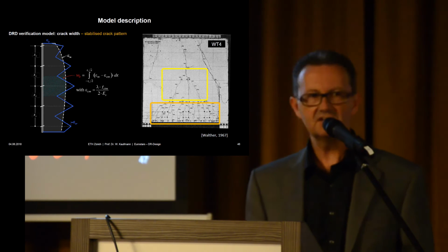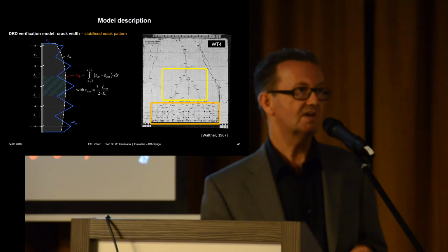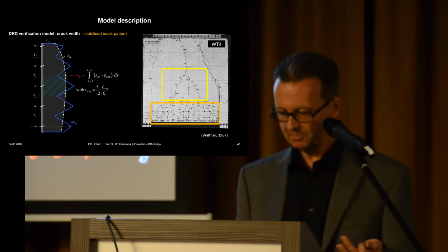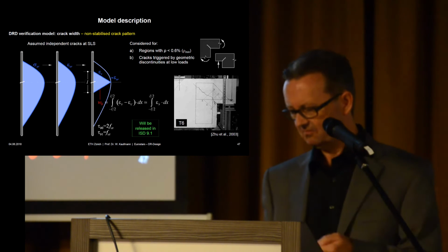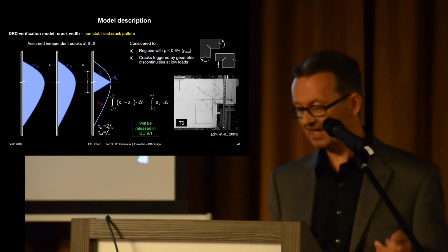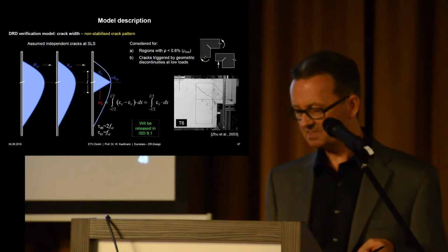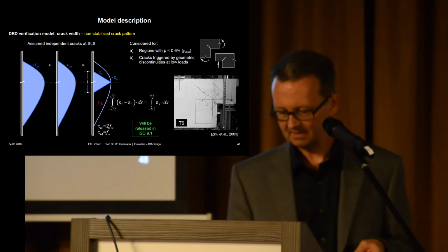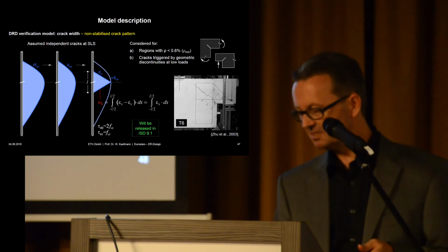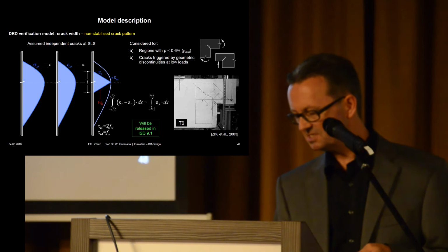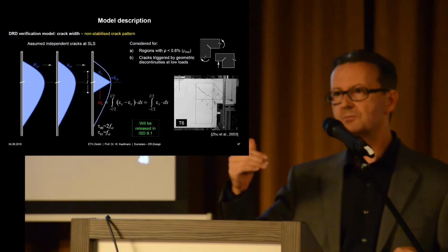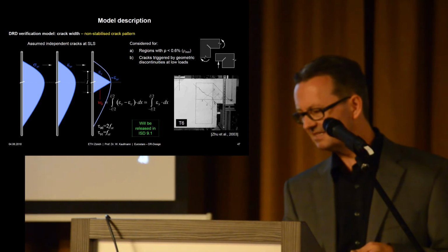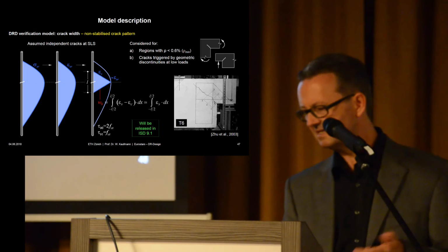What happens up there, where we don't have a stabilized crack pattern? We again have the problem that now from the strains that I told you before, how we estimate the stiffness, we have to calculate the crack opening. And we have a similar situation where you have a re-entering corner, like in this end beam, and this crack appears very early in the loading process, and we don't get the chance to get more cracks in serviceability.